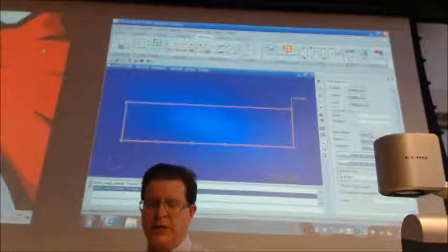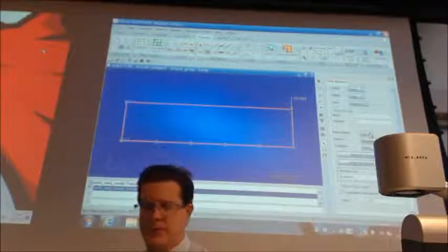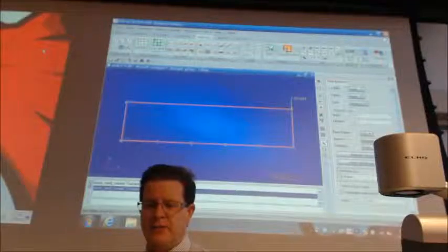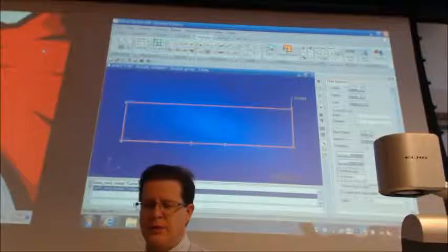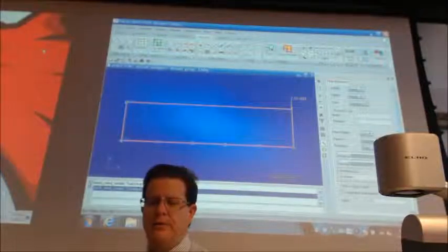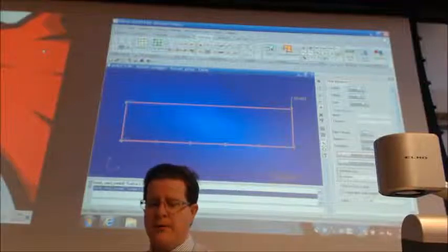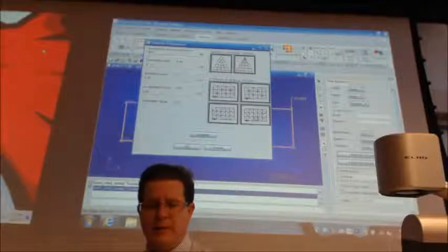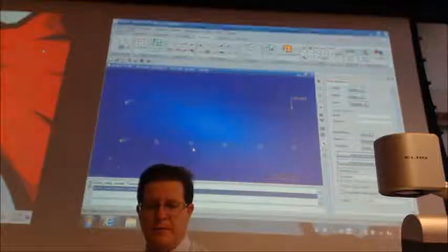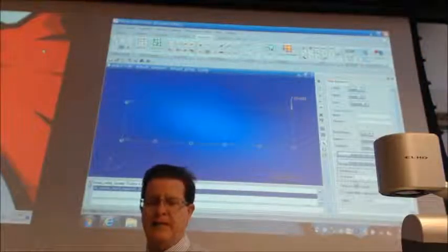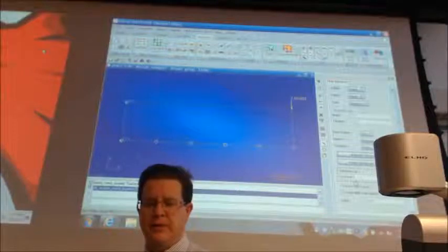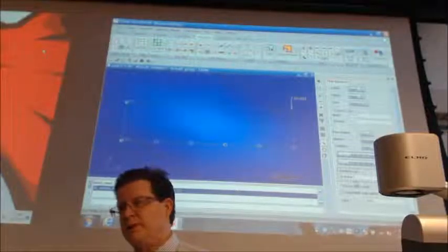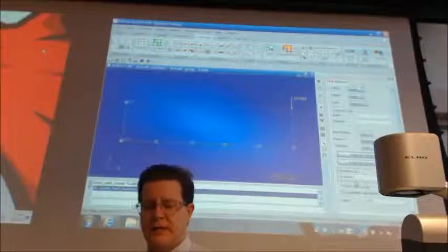We're going to do element shape is tria for triangle, and iso mesh, and we want 3 nodes per triangle. If you pick here, you can do 4, 6, 7, 8, 13 nodes per triangle. Then when you go into the iso mesh, select this bottom right one. You can pick any one, but we're going to work with the bottom right one. And for your surface to be iso, it just means that you have equidistant sizing for your nodes.